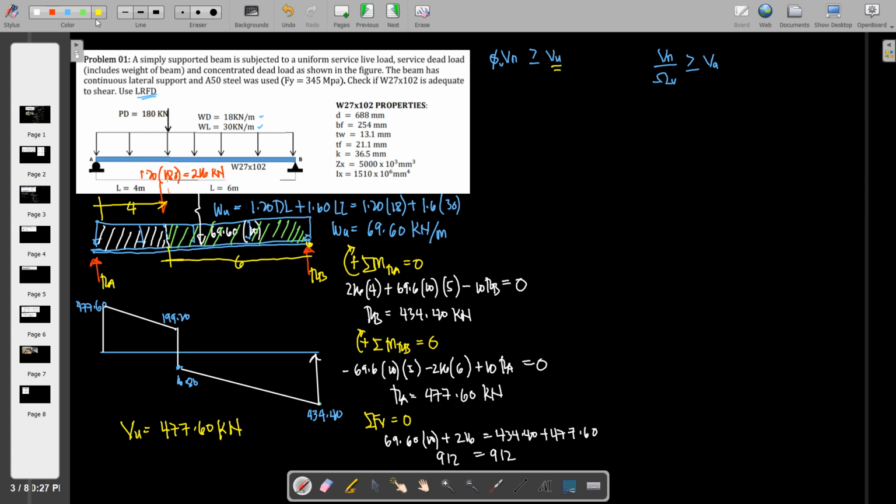So una, first, Vn is equal to 0.6 of Fy times Aw times Cv.